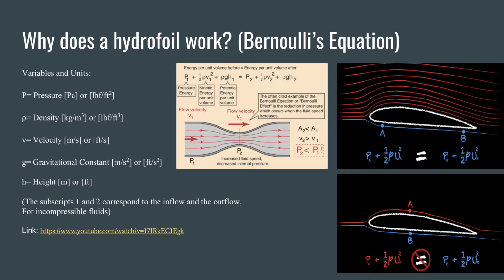The hydrofoil causes the fluid above it to move at a higher velocity, and using Bernoulli's, something must decrease on that side of the equation to maintain the conservation of energy, and in this case it is the pressure. The fluid below the foil has only a slight velocity change, if any change at all, and this provides a steady pressure force beneath the foil.